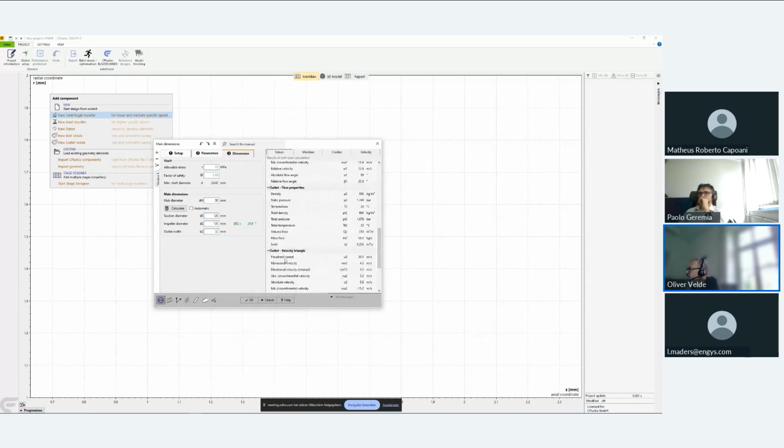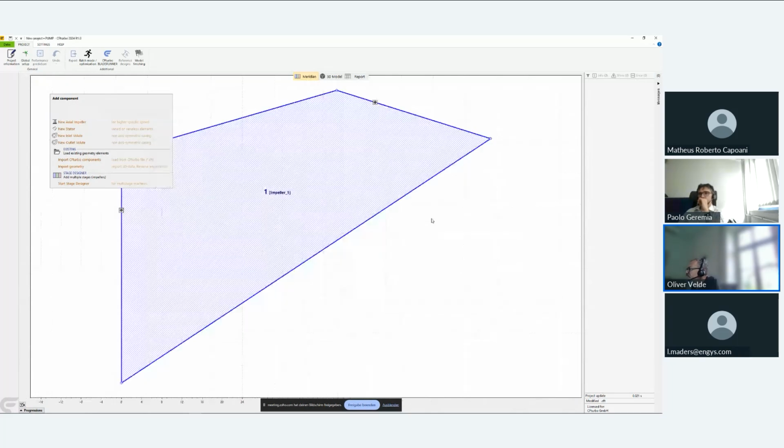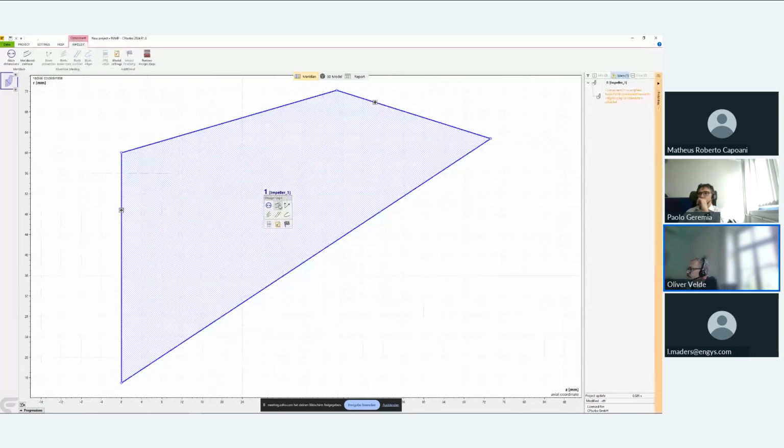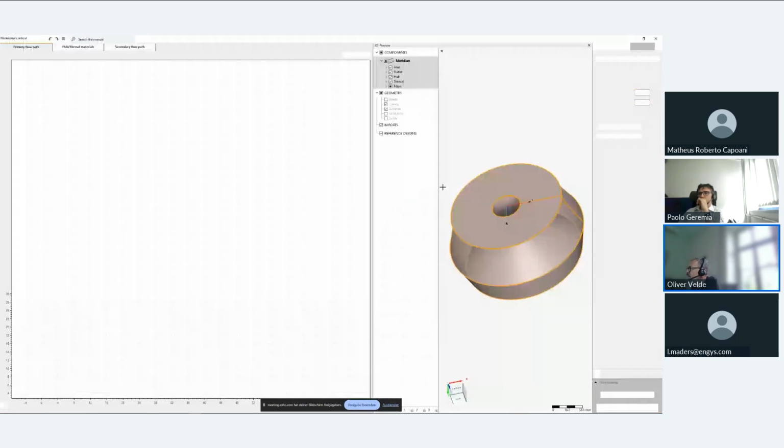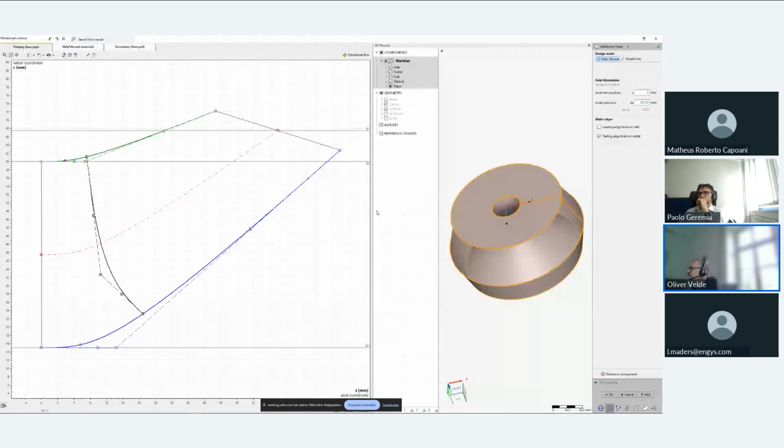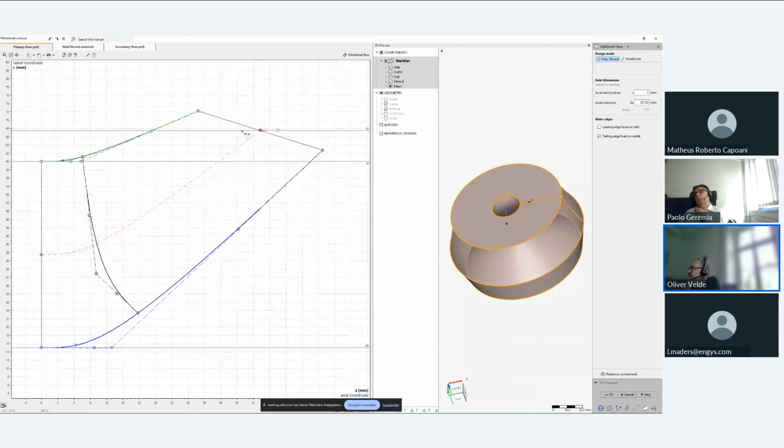Once this is done, I can go to the next design step, which is the meridional shape description. Here, the 3 diameters are the constraints. As I said before, you can only change them at one particular location, which was the first design step. If I would like to change them, I have to go back, but that wouldn't be a problem because everything is parametric.